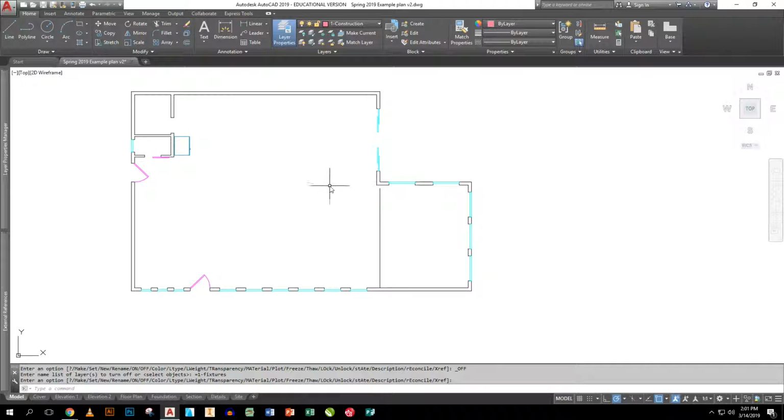There's a set of columns in this building that run down the middle right here, basically where a bearing wall would go, but because we want it to be open, we'll need a beam that runs the length of this building. If we embed it in the floor for the floor joists to connect to, we need bearing along a series of posts down this that will transfer that load to the basement. Now, again, this is a relatively small building. You could do this with steel and things, but right now we're setting it up as if it was timber framed and using some of the timber to help support it as well as be decorative.